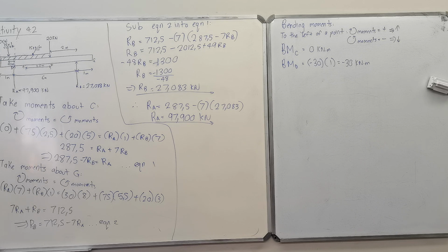Javed, what if they didn't give you that 15 kilonewtons per meter, and they just gave you the force, 75, the force being applied? But they gave you the length of the beam. So you have to work that out. You have to say 75 divided by 5, the magnitude that applies to the beam. Then from there you work out your portion for the calculator. It's the same thing, but you're working backwards.